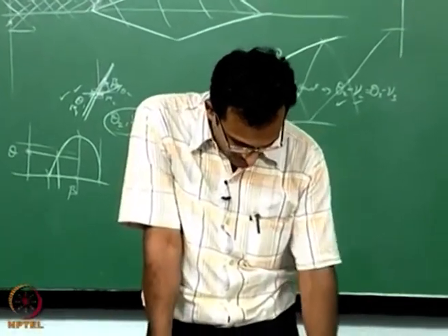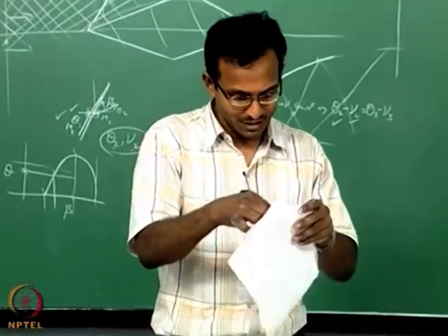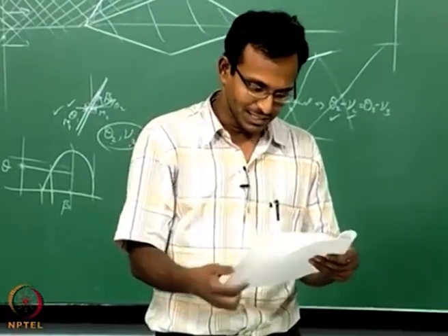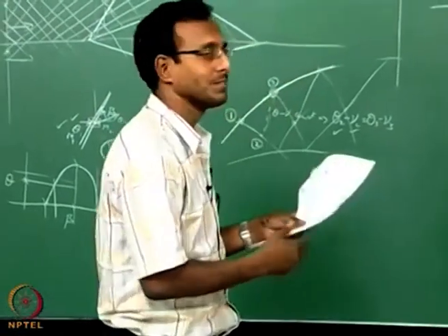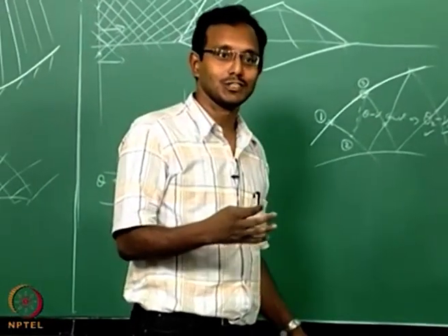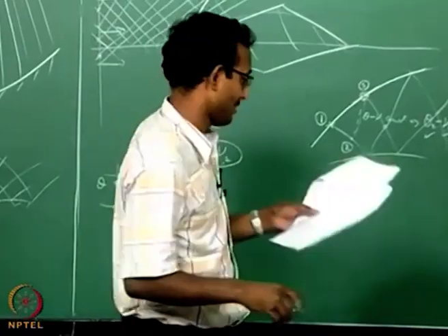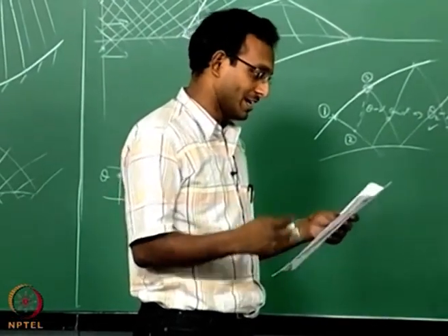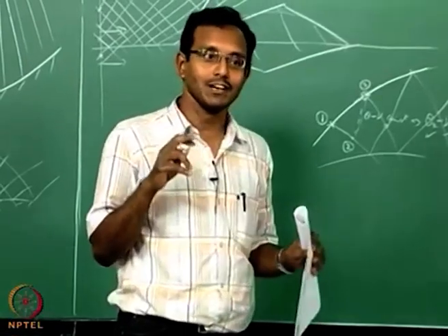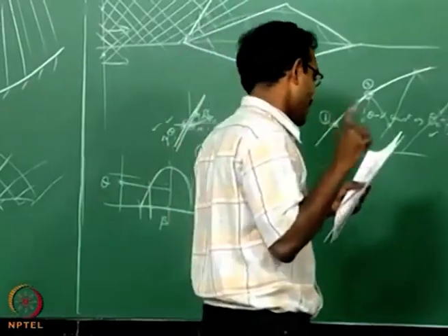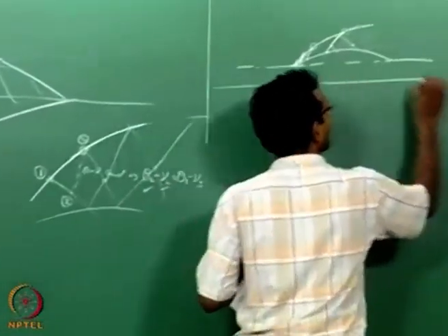So I think I have talked almost about everything in 2D method of characteristics. I will just give you a little bit of axisymmetric method of characteristics. That is, I will just give the equation and say it is solvable, but I will not solve it. If you do the same kind of equations and finally come to a point where d theta plus d nu equal to 0 kind of form, then I will write that particular final expression only.